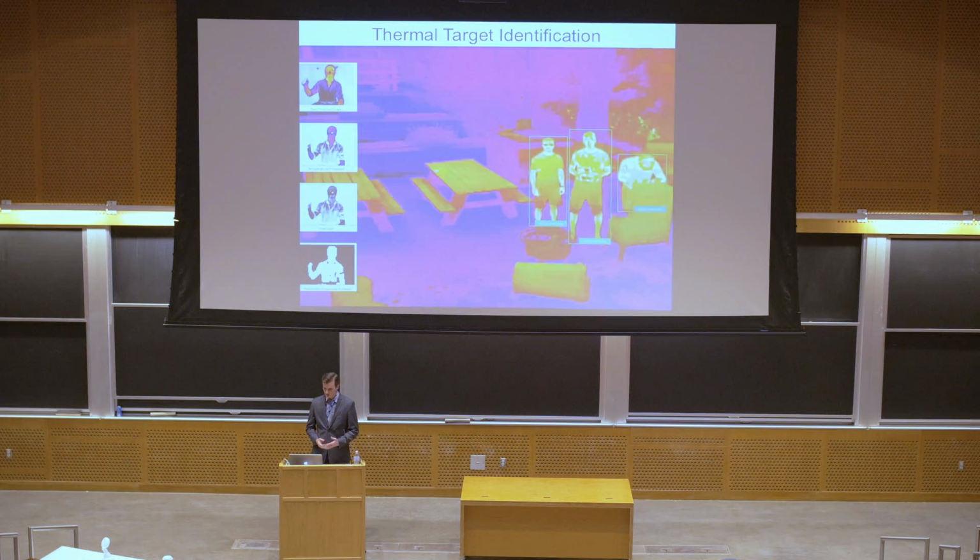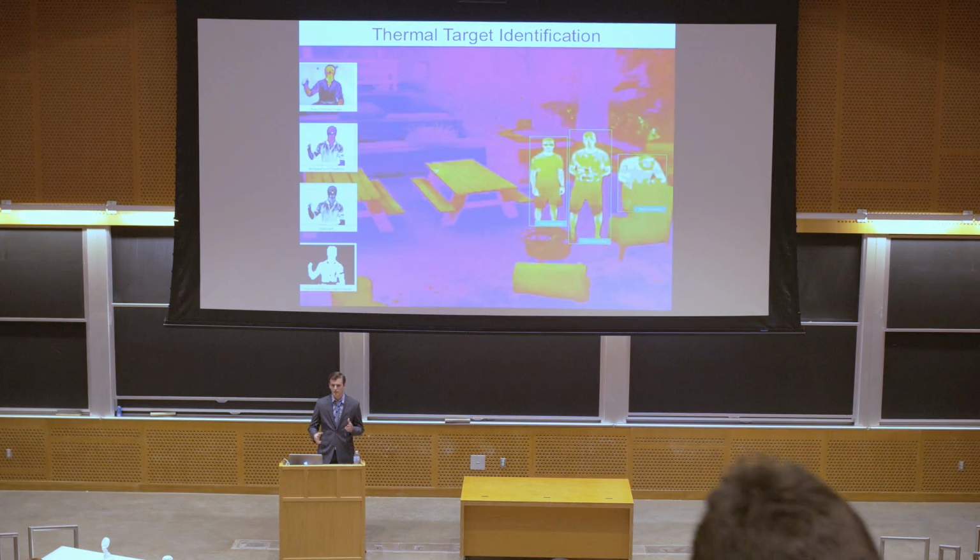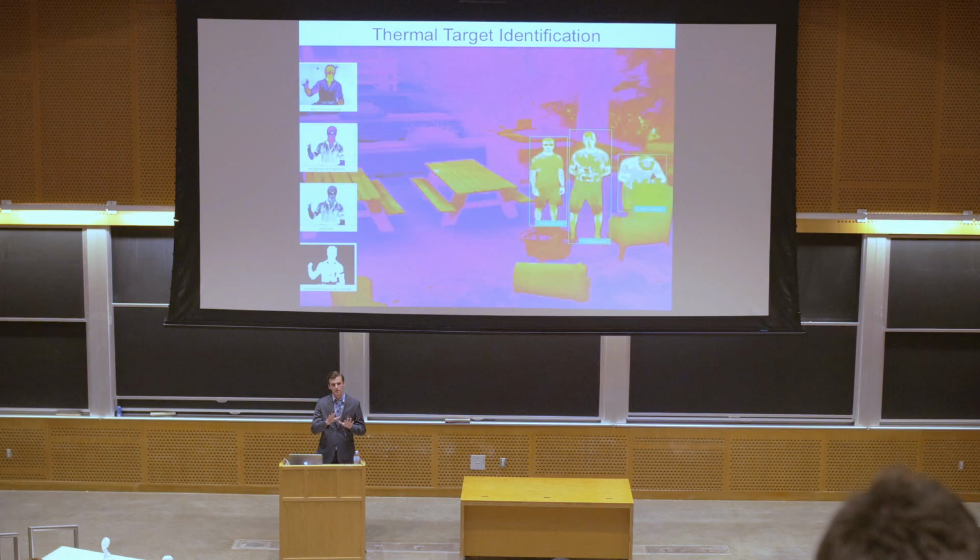One of the main challenges here is that due to clothing and other articles, thermal signatures on humans can obviously not be completely consistent. And so it's very possible for someone to appear disjoint in an image after post-processing, and that would result in an algorithm failure. Some of the gaps here can be filled in using morphological image processing and by looking at different areas of the frame and comparing the frequency of blobs in certain areas.